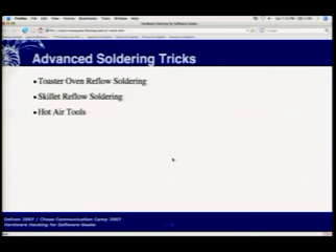Reflow soldering is a process that uses powdered solder and flux to bind the chips to the board temporarily, and then the whole board is baked. The flux burns off, cleaning the parts, and then the solder melts and fixes the part to the board. Usually a commercial IR reflow oven is a two-thousand to many-tens-of-thousands-of-dollars device, depending on controllability and also how many boards you can put through it.